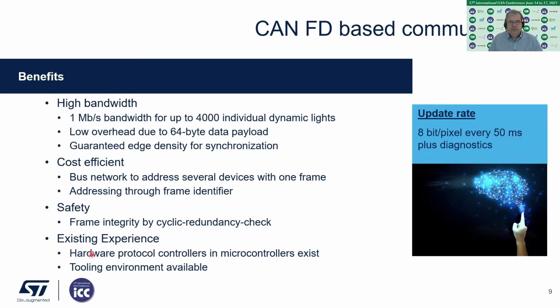First of all, we have hardware protocol controllers and microcontrollers. CAN FD protocol controllers are there, and they are already implemented in hardware in the domain controller. So we do not implement anything in software here. The protocol is already managed. And most important at the car maker side is that the tooling environment is already available. So you can use your existing tools to analyze the network. In case there's any issue at the manufacturing sites or at repair stations or whatever, you have the tooling already available to run your diagnosis. So a lot of benefits from the CAN FD side.